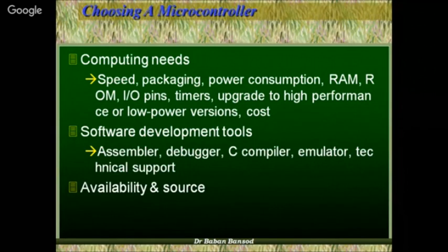As I was telling, one of its features is that it has a 21-bit program counter. So the addressability is as high as 2 megabytes. Because in 8051 what we see is that there is up to 64K, because your address lines are up to 16, so 2 to the power 16 is 64K. It can go up to that.